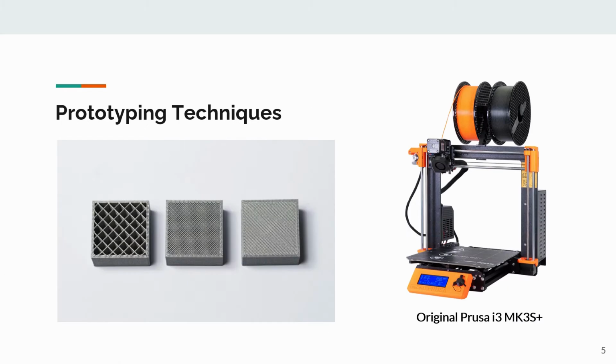Given the attention to detail that was considered when modeling the rocket, the team was able to use on-campus 3D printing facilities for our manufacturing needs. This allowed for quick turnover time, which of course allows the ability to introduce design changes if necessary. The printer we selected was the Prusa Original. The material type we specified was a PLA plastic, white of course, which was printed using a 10% linear infill